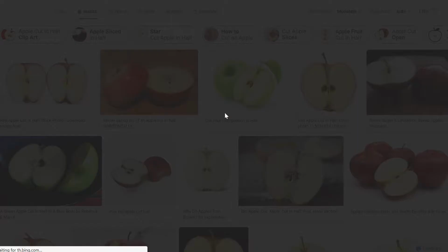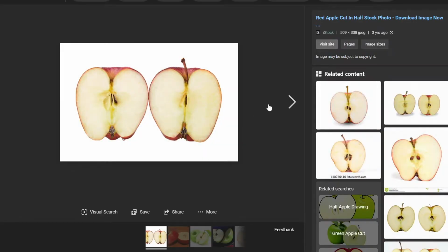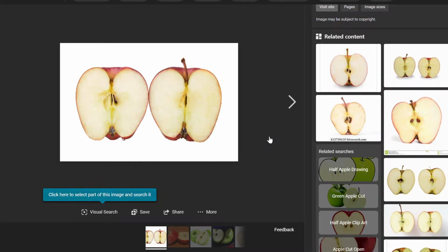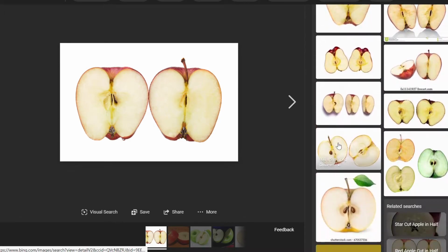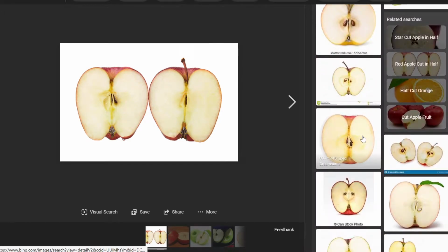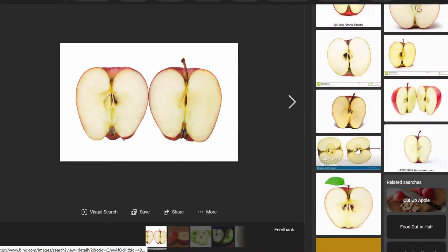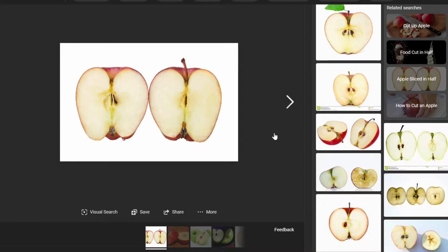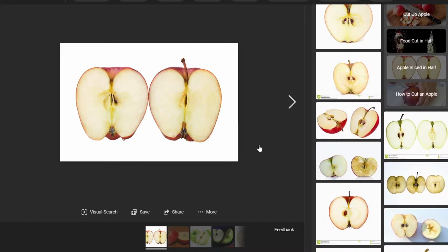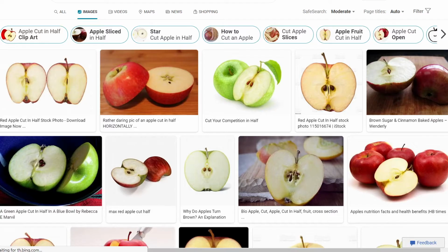Okay, if I told you that we wanted to manufacture an apple and I just showed you the outside of the apple, well, it's not going to give the manufacturer nearly as much information. Now, I could draw some hidden detail. We've talked about hidden detail. Hidden detail is where you draw the dotted lines. But you're not going to have nearly as much information as if you show it in section, where you just show the thing cut in half. And that's a really useful tool, right? So what we do with the area that is actually being cut is we hatch it.